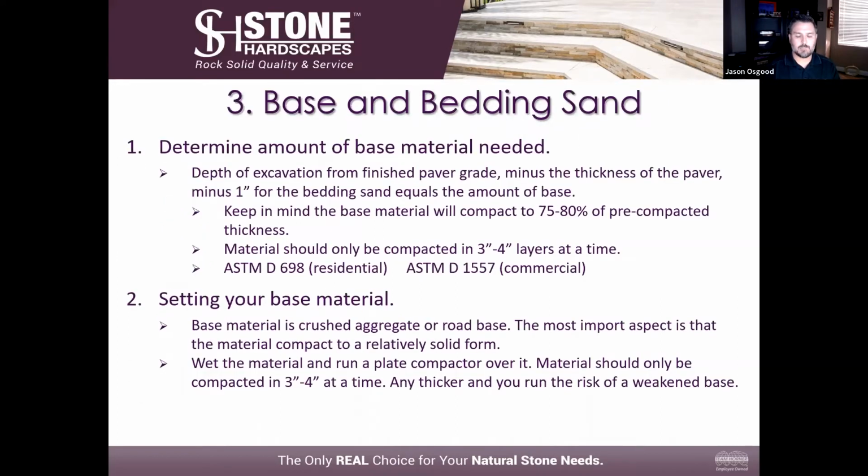So as I showed last month, step 3 of this is the base and the bedding sand install. The base material itself is a crushed aggregate. It lays down below your bedding sand, below your pavers. It gives your pavers a very solid foundation to lay on. The most important aspect of this, whether it's crushed aggregate or road base or crusher run, is to make sure that the product will compact to a relatively solid form.